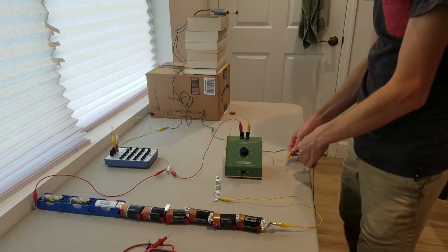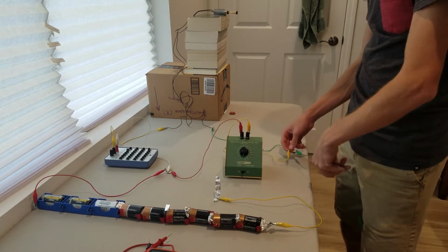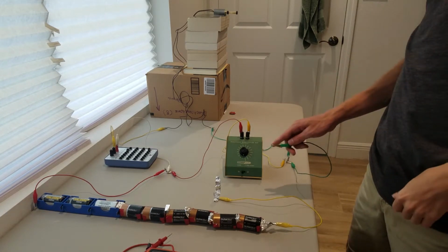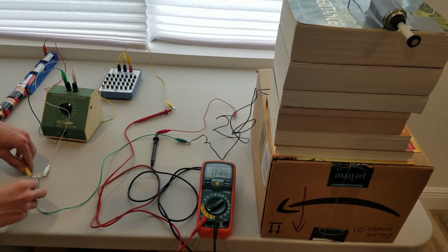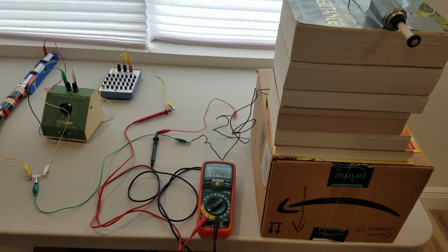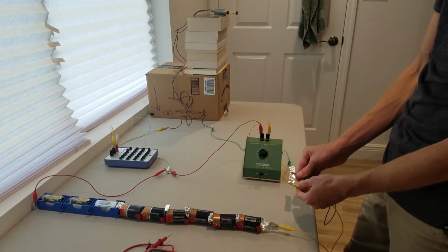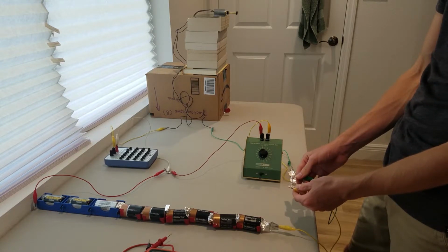When R2 is placed in parallel with the battery, it is effectively being placed in parallel with the rest of the circuit. This means that the current of the circuit is being split between R1 with the motor and R2. We can see here that the current through the motor when R2 is in parallel with the battery is about 0.4 amps. The current through the motor before R2 was added was 0.48 amps, but I lost the footage of that, but just trust me, that's what it was.